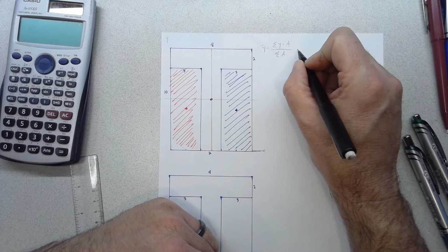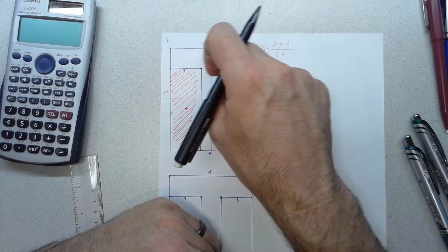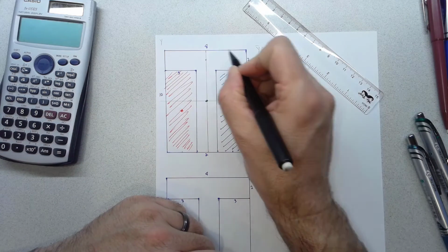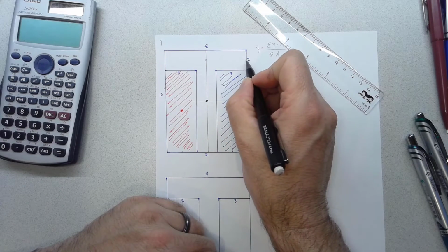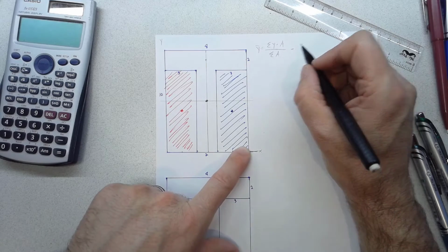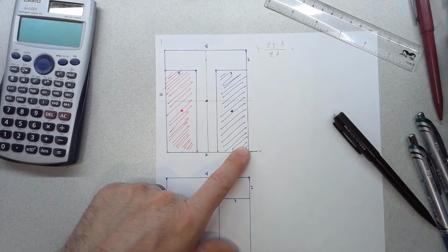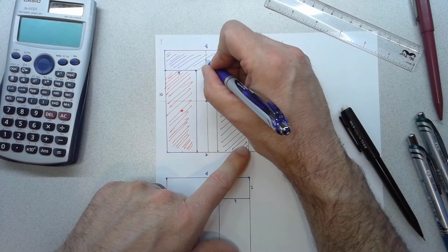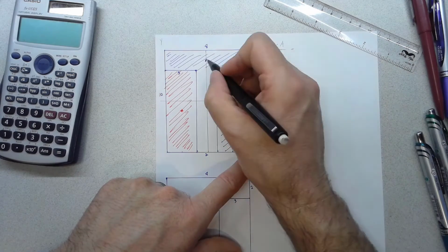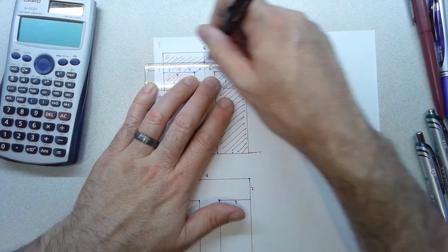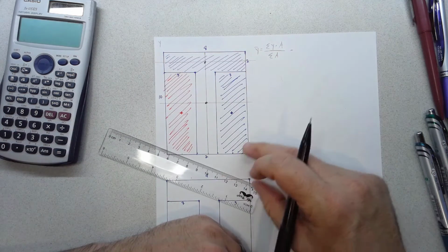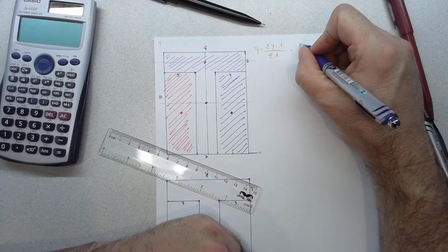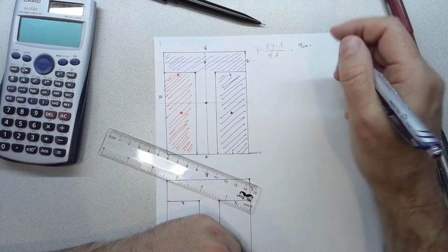So first, let's look at the area of this top flange. Its centroid, we know, is going to be located somewhere right about there. It'll be centered because it's symmetrical, and up 1 from there. So the distance from the bottom of the shape to the centroid of this upper, let's add some color here, distance from here up to this centroid. So this is the centroidal neutral axis of just that top flange. That distance is going to be equal to, from here to here is 8 plus another 1. So the distance for that area is going to be 9 centimeters, times the area of that, which is 2 times 8, so 16